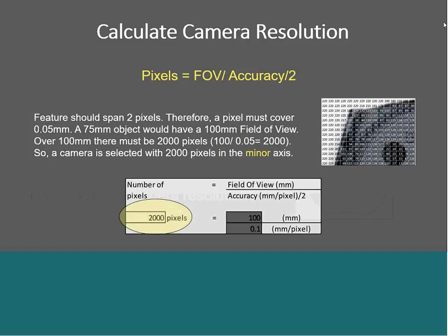The reason that we say 2 is, if you look at the right-hand image, basically that is the part, and that's the pixel matrix with some grayscale values superimposed over the part. Now, the system cannot detect a transition from light to dark, or lighter to darker, in only one pixel. So you need 2 to detect a change.